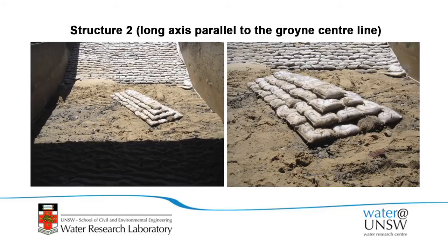We also looked at them with the bags pointing out to sea. So the long axis of the bags here is coming off the shore. This is a lower example of it. So the bags are pointing out to sea here. That was part of the impetus for this testing, which is potentially a better way to build the groins. I'll give you the answer on that towards the end, but I'll show you a few other interesting findings.